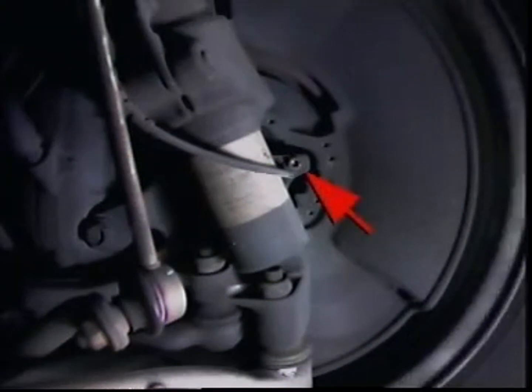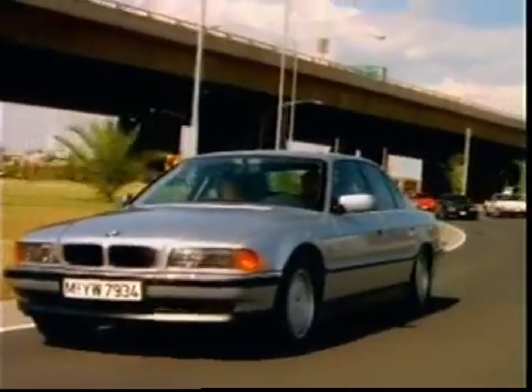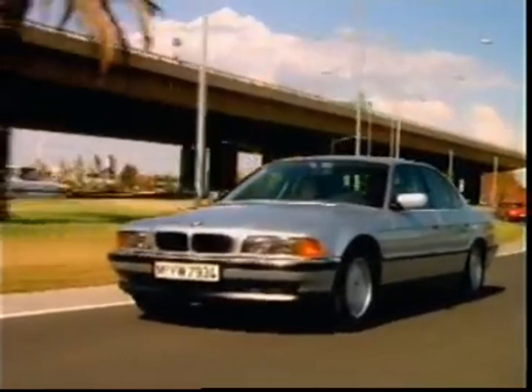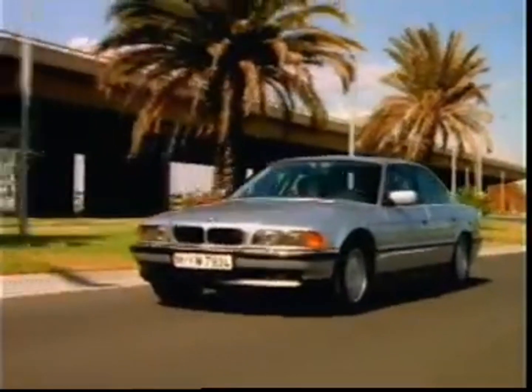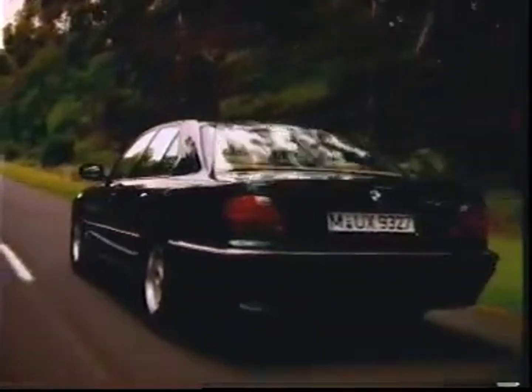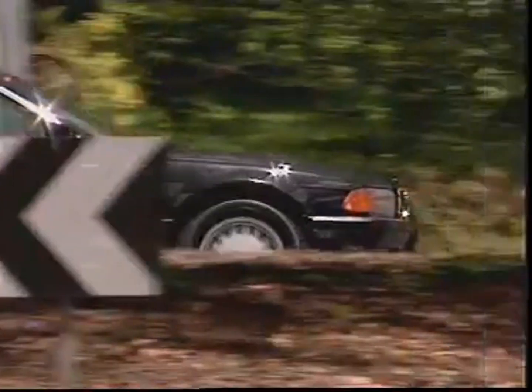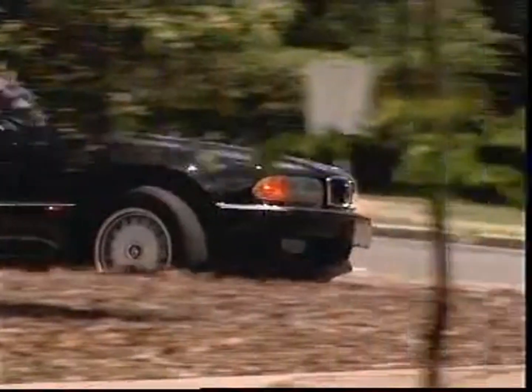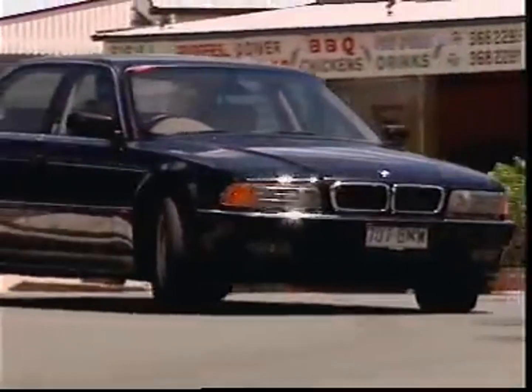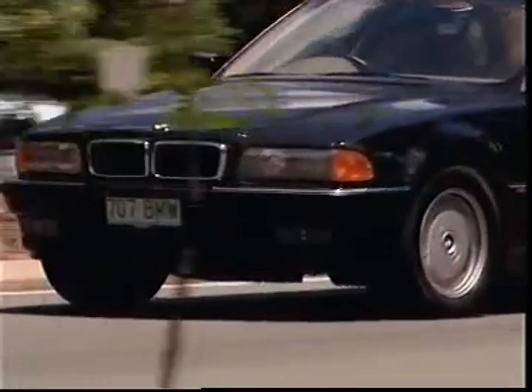For data from the wheel sensors to be accurate, it is essential the two front wheels have the same dynamic circumference. This is monitored continuously by the diagnostic circuits. Any discrepancies, perhaps from different tyre pressures, will deactivate the corner identification.